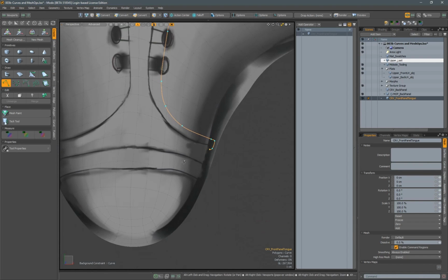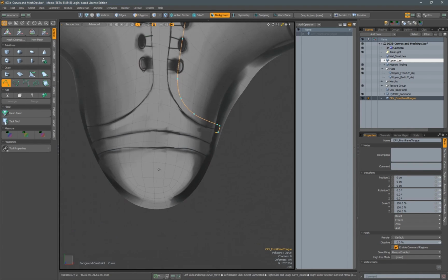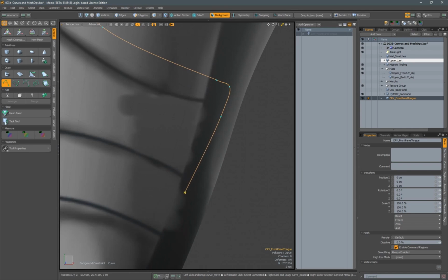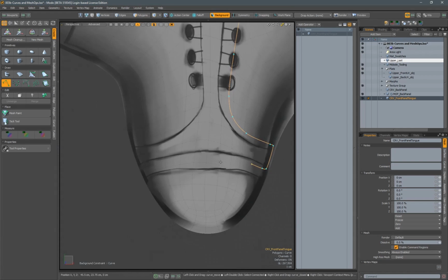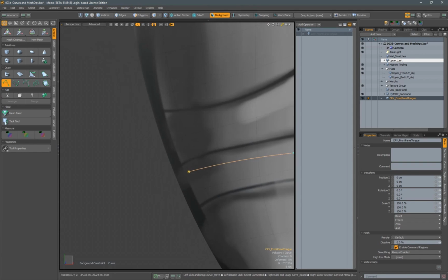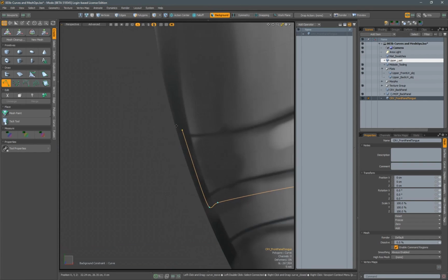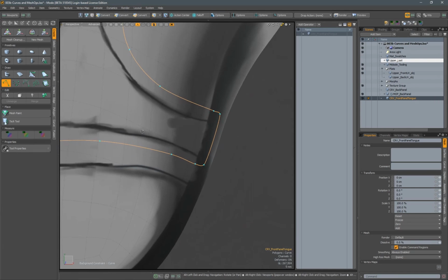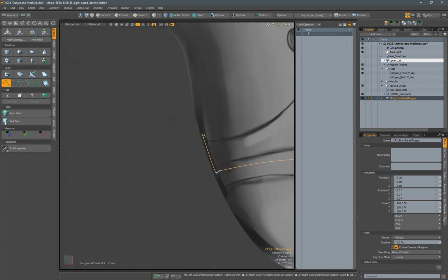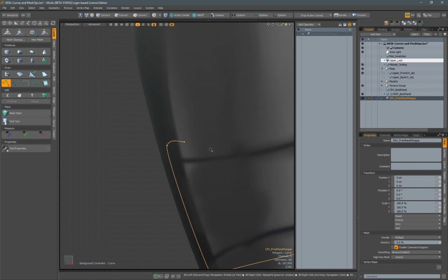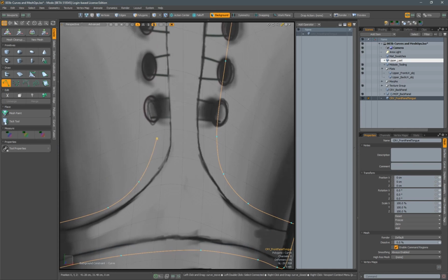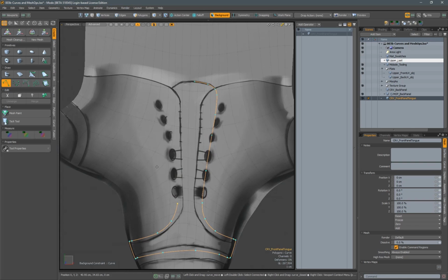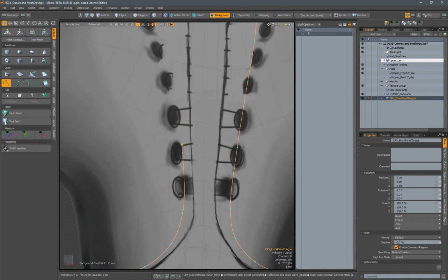All right, so we have this panel right here, the toe cover, or the toe cap, and what we want to do is tuck that underneath there. So let's go ahead and bring this curve over here, and we'll make sure that it goes underneath right there, because the toe cap starts right here on this sketch line. Let's try and duplicate the amount of curves we have on the opposite side. So we had 2 over in that area. This doesn't have to be dead accurate because it's going to be tucked underneath the other panel.